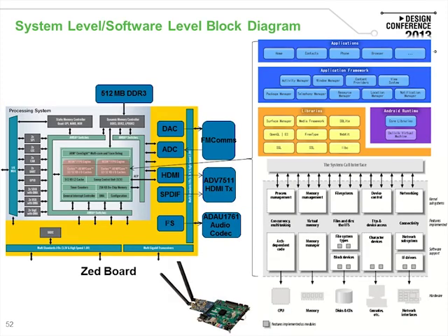When you look at the software system architecture, and we talk about software drivers, we're talking about the device driver that hangs out over here on the Linux side, whether that be Android or just Ubuntu, which is what we typically run. You still have all your system libraries, your applications, and your application frameworks. ADI does provide both the devices and device drivers, provides the HDL, and provides a small application to actually look at things.